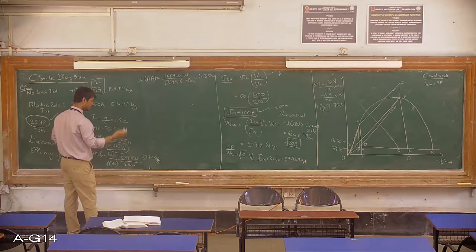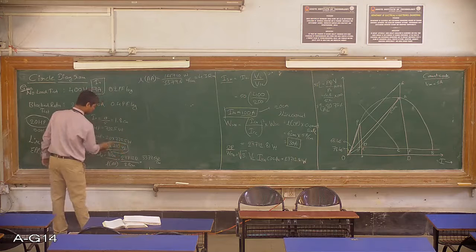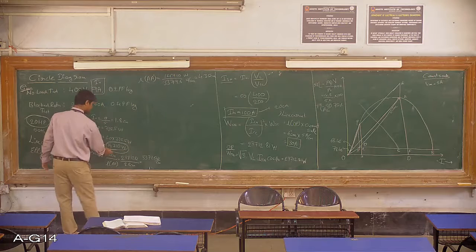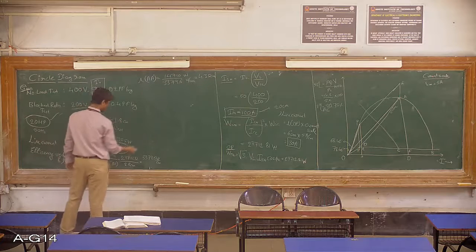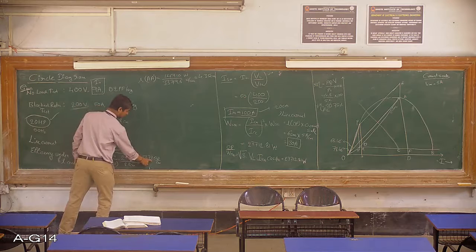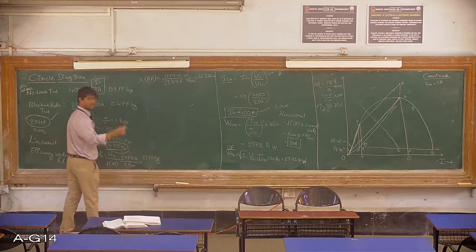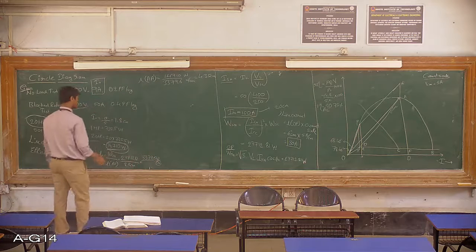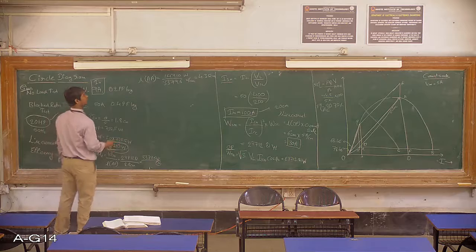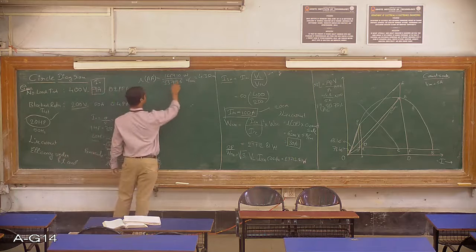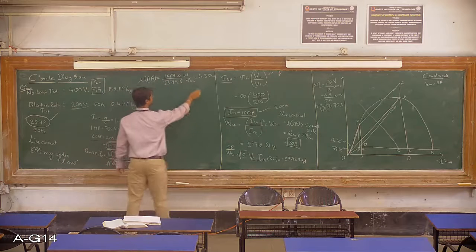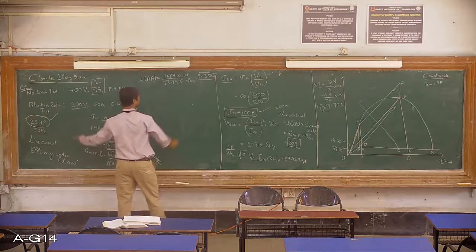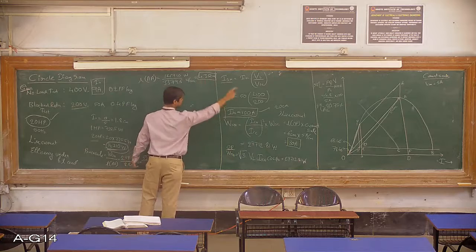But now I cannot show this 14,710 watts in the graph page, because graph page is in terms of centimeters, in terms of length. So convert this 14,710 into length in centimeters by using the power scale. We know that power scale is 3,379.6 watts per centimeter. That means for 1 centimeter it is equal to 3379.6 watts. So 14,710 divided by 3379.6 gives this output in terms of centimeters. 20 HP is equal to 4.35 centimeters in this graph.